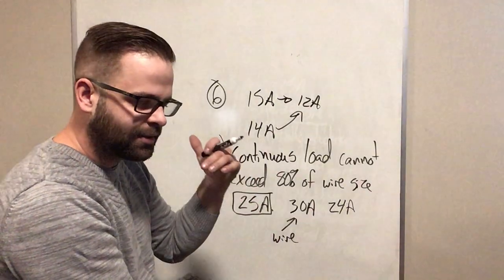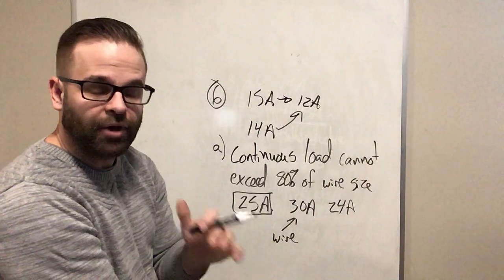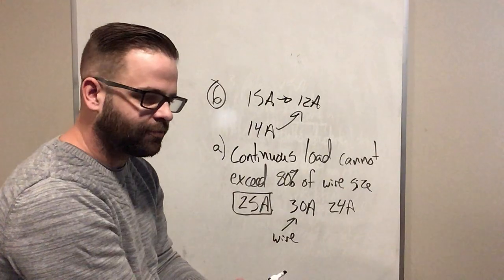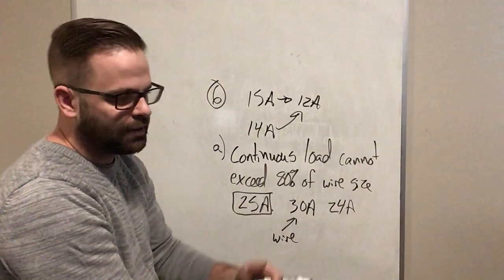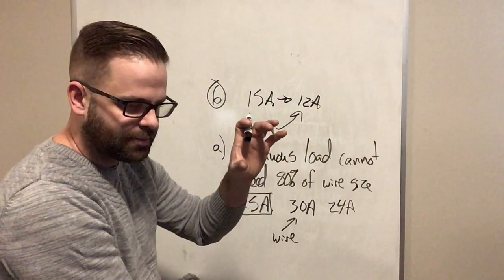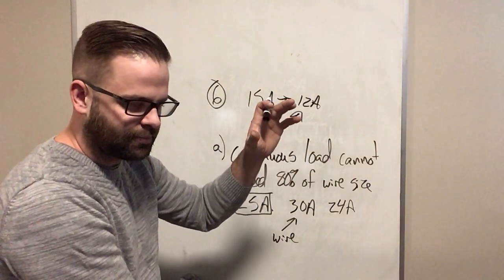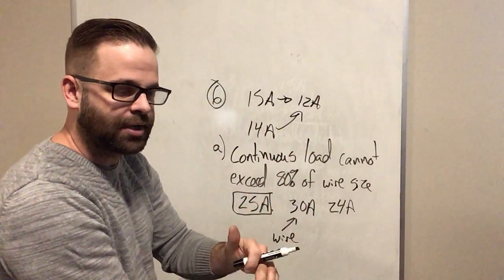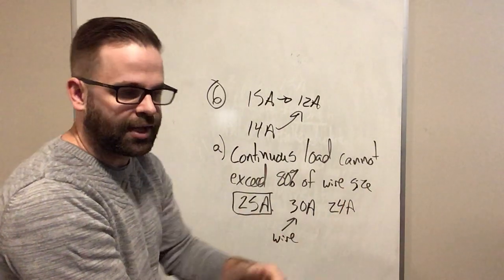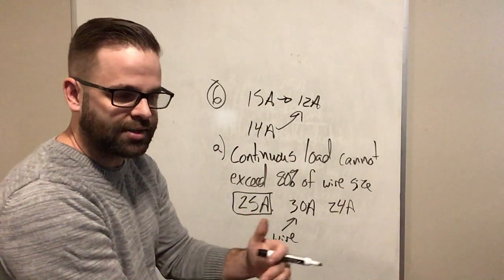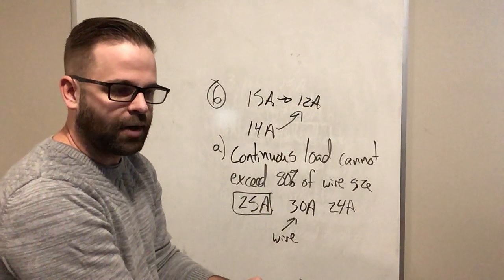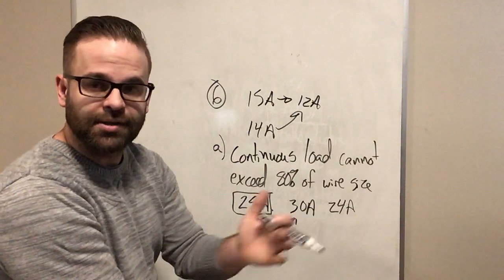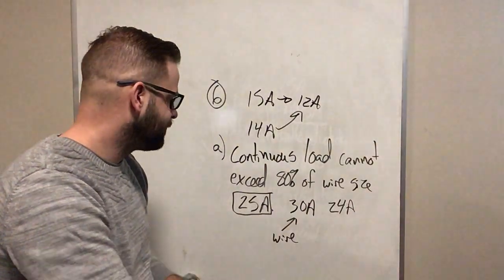So a breaker size, and looking now from the other way, if a breaker is sized for continuous duty at 80%, I'm looking at my breaker size, it's 80%, so it's let's say a 50 amp breaker at 80% is 40, so that just means that my continuous load calculated can't be larger than the 40 amps, and also my wire size that I put in, that wire size has to be large enough that the calculated load doesn't also exceed 80% of that value.